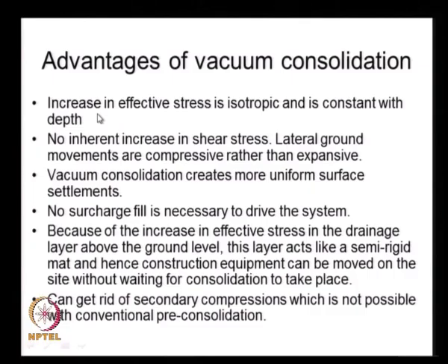I will briefly outline some of the advantages that we have seen. The increase in the effective stress is isotropic and constant with depth, and the lateral strains that we induce with vacuum are compressive, whereas with normal surcharge there is an outward movement, and there is no increase in the shear stress. That means lateral ground movements will not take place, and vacuum consolidation is known to result in more uniform surface settlements, and we do not have to apply any external surcharge pressure to drive the consolidation.